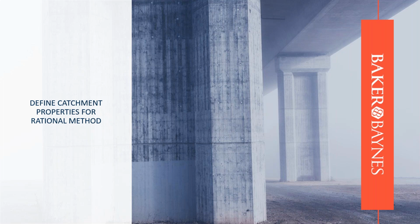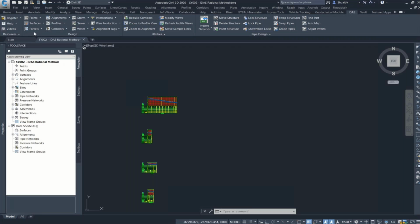The next thing is defining the properties. Now, this is where we would normally use Excel sheets. I remember having my own Excel sheets, put all the formulas in, your rainfall intensity, all of those things, right? Calculated, formulated, and you just copied them to each project location and edited the data, your C values, your roughness, everything. You normally had a formula for this type of thing, especially for the rational method. But this is a very technical part of it. So I am not going to explain each and every engineering theoretical application.